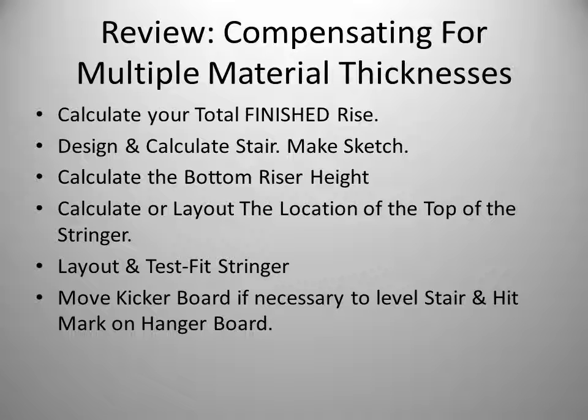Once we've designed and calculated our stair, we can calculate the bottom riser height. Use the formula on the previous slide to calculate that bottom riser height. We can also lay out the top of the stringer on the hanger board. And then we can lay out and test fit our stringer. Remember, if you need to move your stringer up or down, moving the kicker board will change the angle slightly and change the position of the top of the stringer.